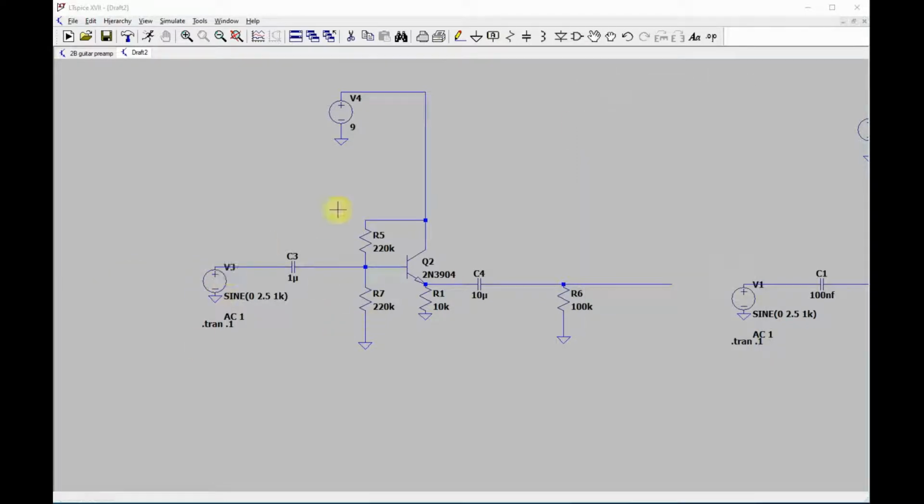so how do you choose these values? A lot of times people will choose it so that this right here times HFE, if you make that much larger than this, you can just ignore it. And that's a common thing engineers do. They'll make this arbitrarily large, or they'll get a really high gain transistor, and then you can just ignore that and just look at this stuff.